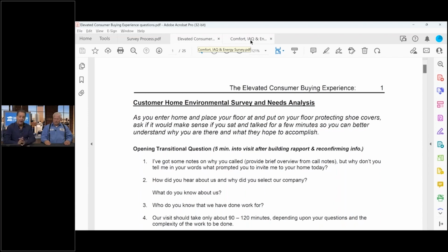And so yes, I'm concerned about my health. If they've got fecal material, I'm putting on a gown. Yeah. So put on the Tyvek jumpsuit, right? And then you put on a respirator, maybe even goggles, right? And some latex gloves, and you go full commando into the thing. And you're basically crawling the crawl space and crawling the attic and whatever. Basements are not as bad in most cases, but it's crawl spaces and attics that I'm going to do that for, because again, I want them to know that your house breathes uncontrollably, and whatever is there, unless it's sealed, is going to be in the air that you breathe.